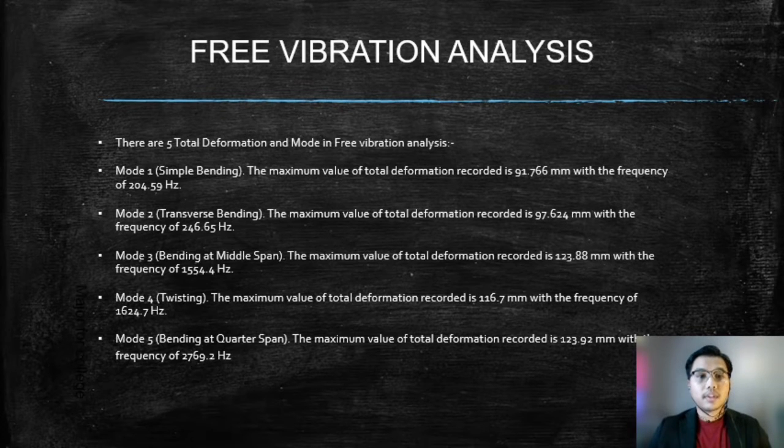Mode 2, transverse bending. The maximum value of total deformation recorded is 97.624 mm with the frequency of 246.65 Hz. Mode 3, bending at middle span. The maximum value of total deformation recorded is 123.88 mm with the frequency of 1554.4 Hz. Mode 4, twisting.